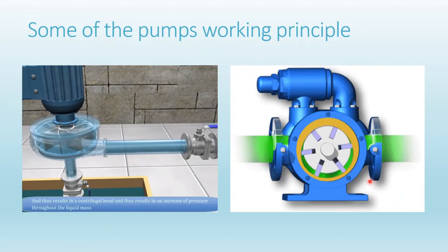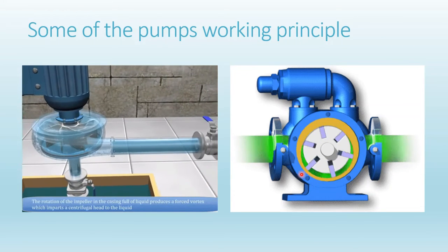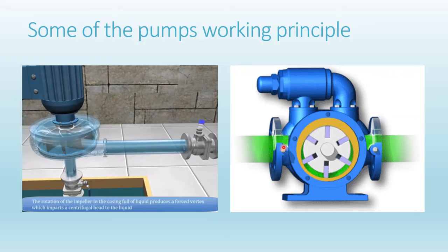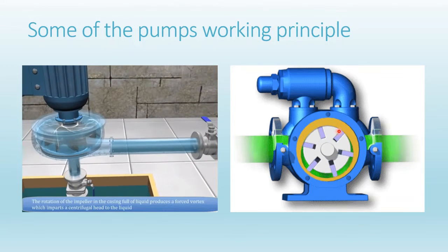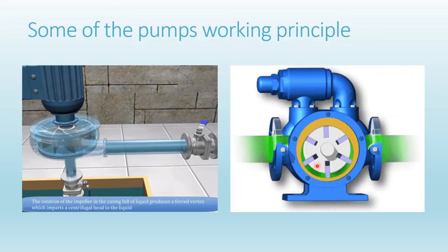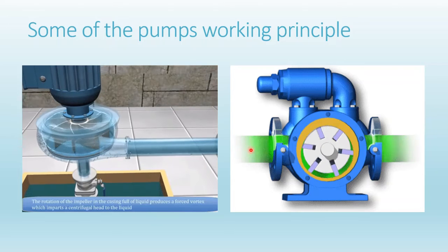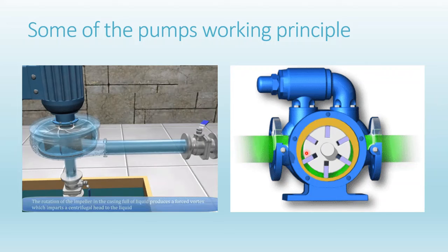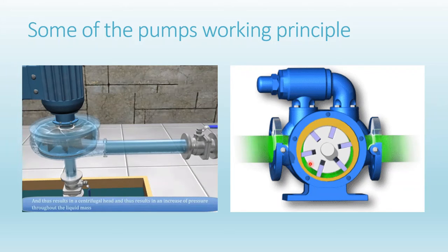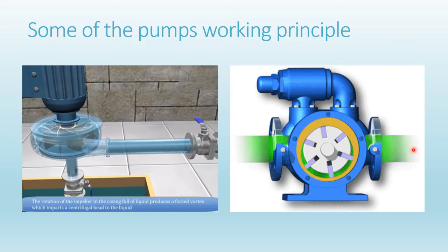This is an example of positive displacement pumps. In this, the material will be transferred from this side to this side. This is the pump's main working principle. This is a cam-like design, with an internal eccentric shape. The vanes slide in these slotted parts. When the vanes come out of the slotted parts, the material enters the cavity between the two vanes, gets pressurized due to the internal eccentric shape, and is delivered to the delivery side.